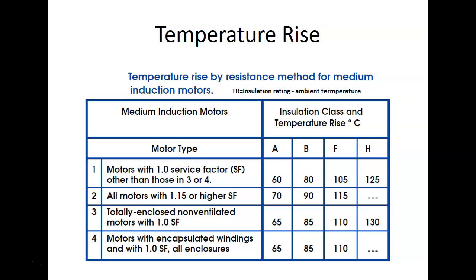When this guy here is generating a north pole, this guy here is generating a north pole. So what's the tendency of these windings to do? Like magnetic poles want to do what? Repel. So the transformers do what? Yeah, they're moving back and forth. The problem is, if you have a lot of motion, the wires can rub against each other, and then you have two wires touch, right? Understand? And that creates what we call a shorted line.